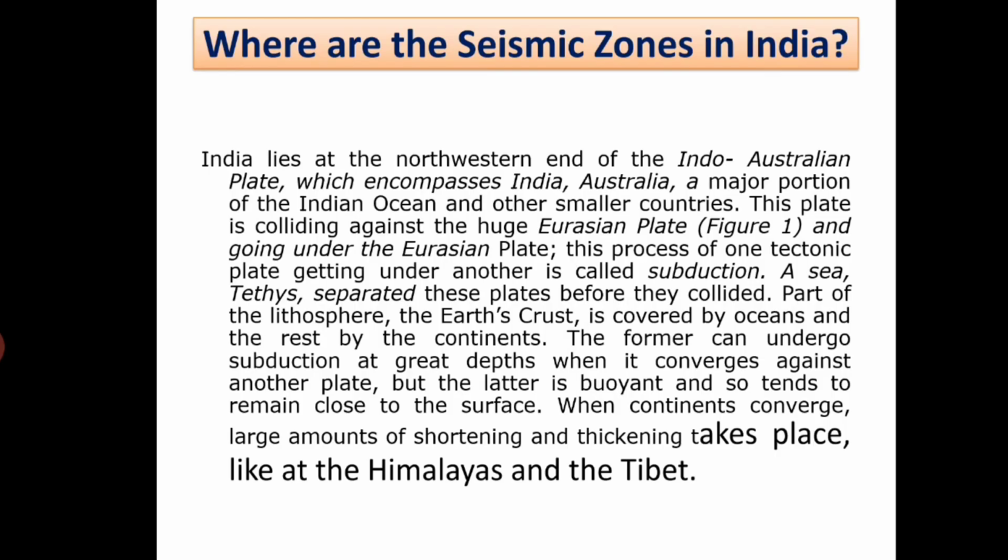Now, what are the seismic zones in India? India lies at the northwest end of the Indo-Australian plate, which encompasses India, Australia, a major portion of the Indian Ocean, and other smaller countries. The plate is moving against the huge Eurasian plate, as we will see in the figure. It is going under the Eurasian plate. This process of one tectonic plate going under another is called subduction.